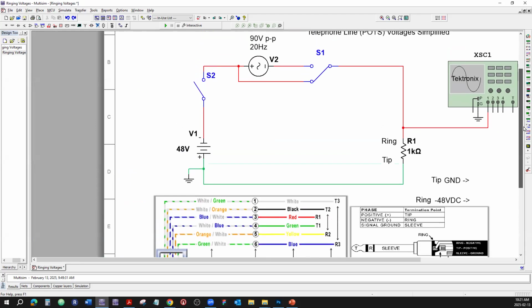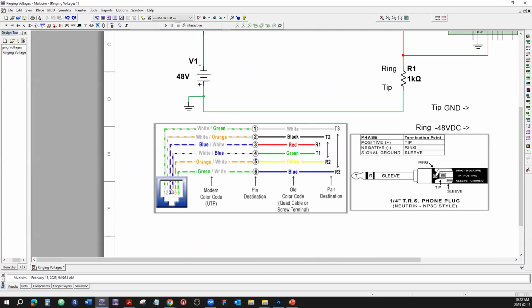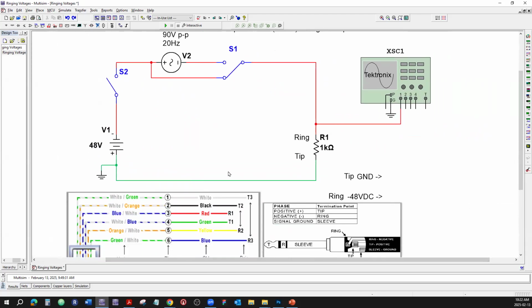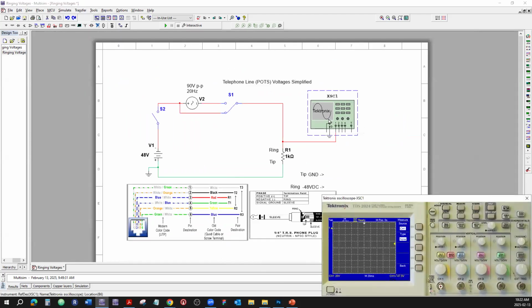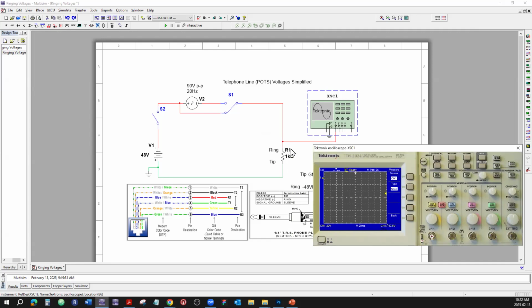Now, how is it that the phone rings? At the jack, as I said, there is that idle minus 48 volts DC just sitting there. Okay, so let's scope it. I multi-simmed it, put it on the scope. So let's turn the scope on here. And do we have it turned on? Yes, now we have it turned on. Now, over here is the battery that is basically provided by the central office, which is the building where all the automated circuitry is for the phones.